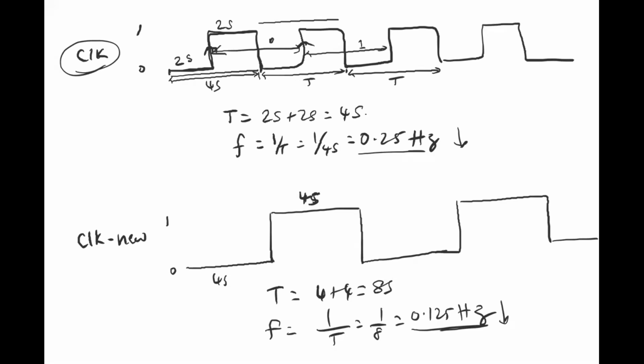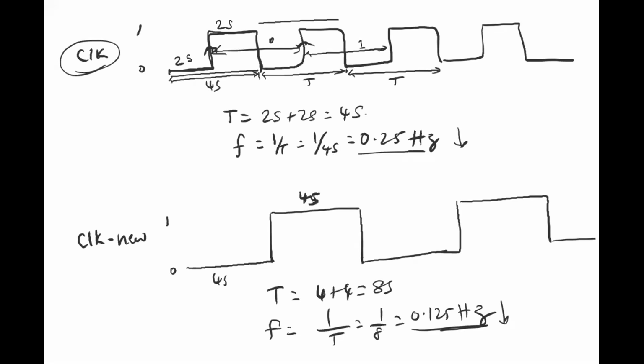So now we'll understand one important concept. In the case of division that we did earlier, from this point to this point is one clock cycle. So you're waiting for one clock cycle to flip your signal. You can do something really similar: you can say, I'll wait for 2 clock cycles and flip my signal, or I'll wait for 3 clock cycles and flip my signal.